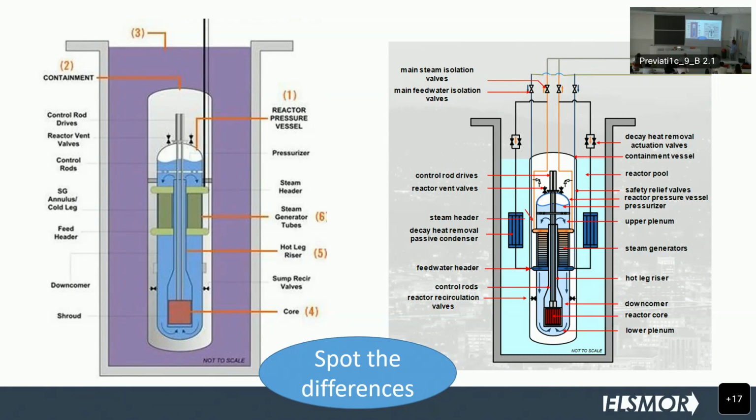Basically, originally, they just opened these valves and had natural circulation through the wall, natural circulation and cooling to the pool. So basically, this was just another way of putting the decay heat into the pool. This was also a way, if there was some sort of overpressure accident or some other accident, to basically ensure the cooling.